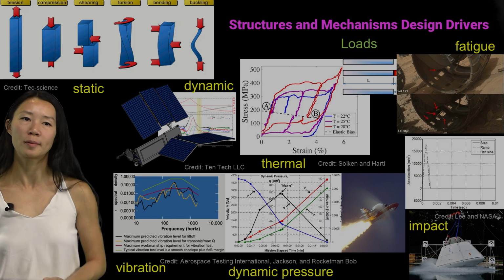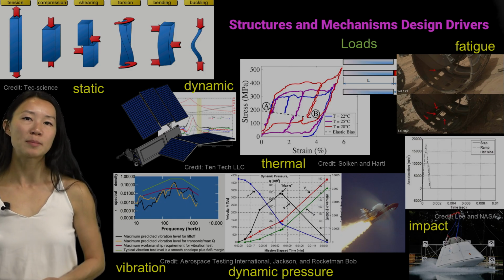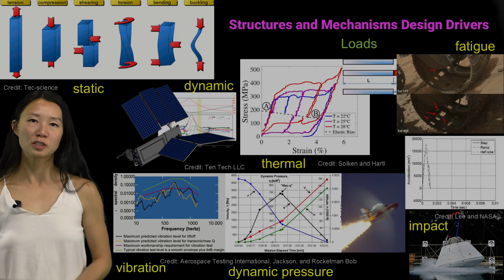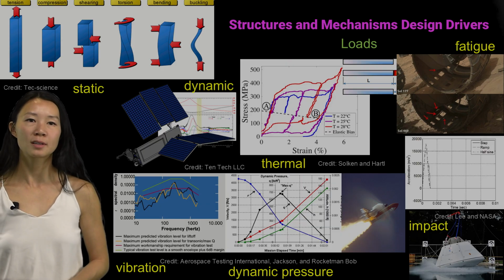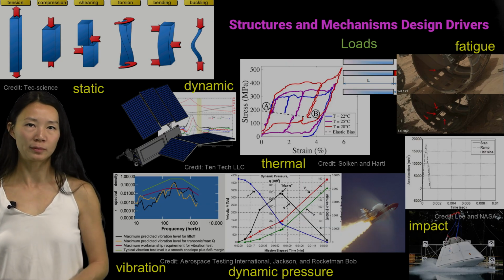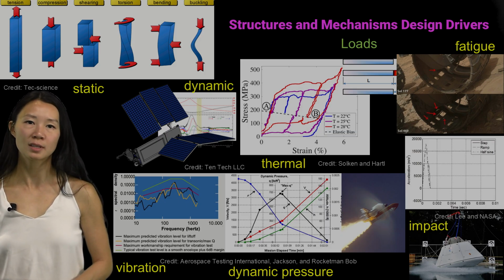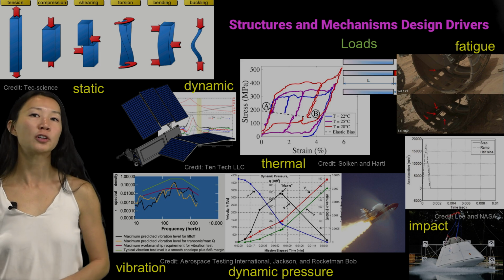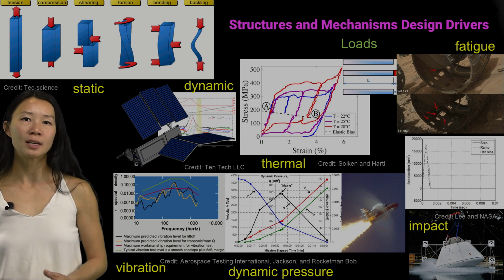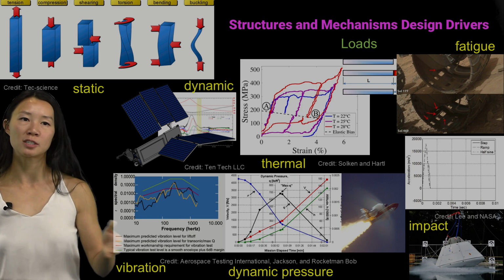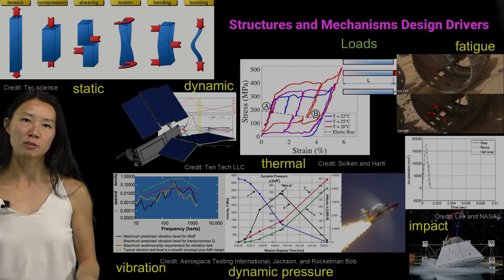This is critical for orbiters and landings during ascent and atmospheric entry. Overall, launch loads drive most of the loads for orbiters, shock and impact dominate for landers, mobility and fatigue are central for rovers, and flutter and vibration are key for UAVs. Understanding the load environment across the full mission timeline is what guides a structural engineer.